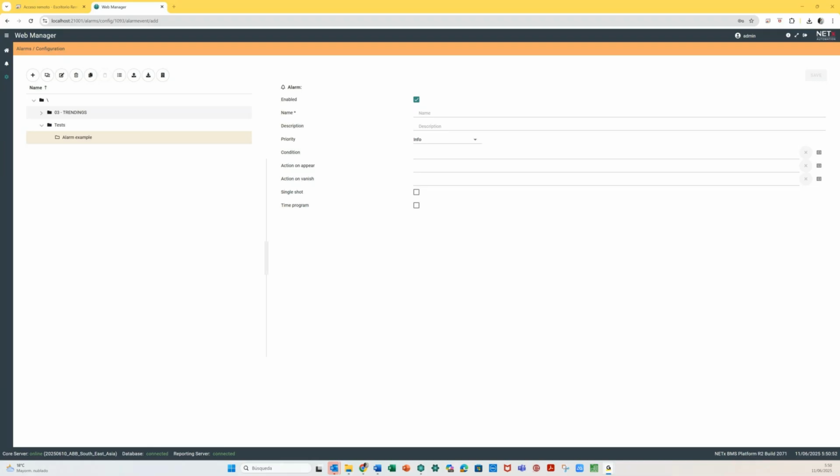So you have to do this logic and create an item that is the average, or an item that is the difference between this and that. And then if this value is above the limit, then yes, you can trigger an alarm. But this condition has to be done before, because the trending is just historizing, and it makes no sense, in my opinion, to get a value from the database calculated by the BMS. You can do it in advance and just monitor this.